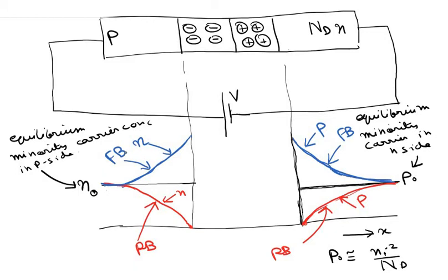Now as this diode gradually goes from forward bias to zero bias condition, in case I apply an AC voltage source, this excess buildup of minority carriers just outside this depletion region must actually be removed.